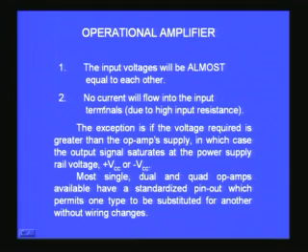This is because in general the operational amplifier input resistance is very large. But there should be a finite current, because you can imagine the input stage we have already discussed is nothing but a differential amplifier, and therefore the bases of the two transistors which perform the long tail pair will be the input stage of any op amp.